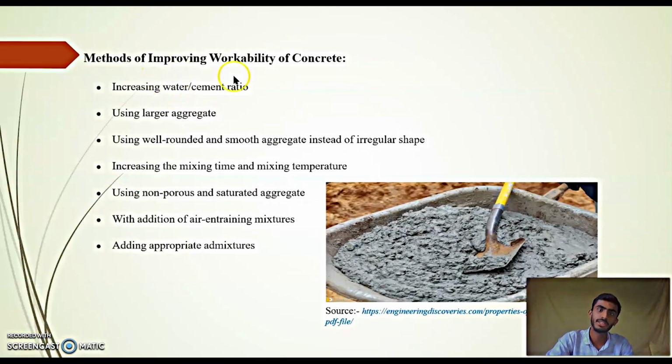And here are some methods for improving the workability of concrete. As we learned about these factors, the methods for improving workability depend on them. Therefore, increasing the water cement ratio. When we increase the water cement ratio, the workability of concrete will also increase. As we know, water acts as a fluid and increases the fluidity in the concrete.